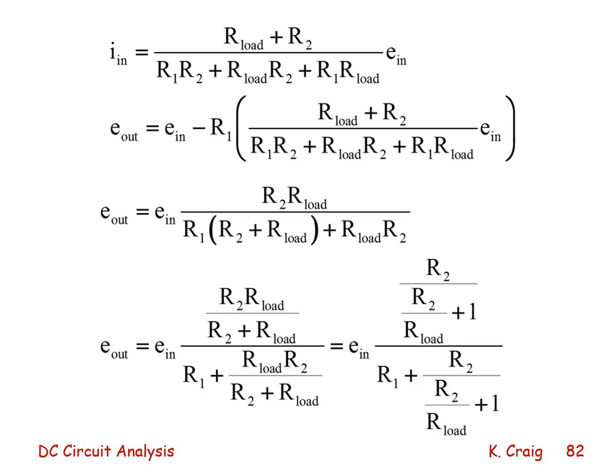But in the end, we get our equation for E out equal to E in times this ratio, which is the same ratio we obtained when we considered the entire coupled circuit: ideal voltage supply, voltage divider, real voltmeter.